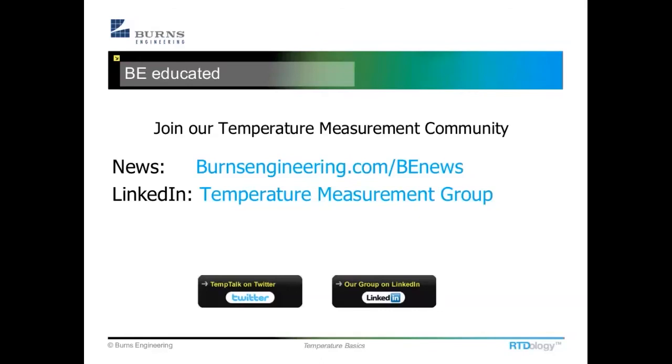Aha. We have more information. Yes, here it is. High accuracy RT. Yeah, well then the 0.03 might be pretty realistic. Our calibration uncertainty for an industrial grade probe is 0.025 degrees C or 25 millikelvin. Depending on how it was being measured, that 0.03 number could be pretty realistic. I would think it would have to say plus or minus, though.